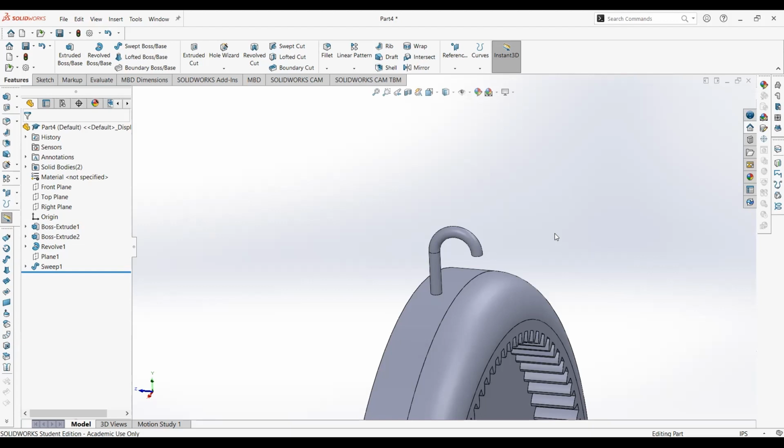Go to circular profile, type 0.125. If you wanted a different profile shape, like a diamond or a square, you could use that tool. But for a circle, the circle was just to show you how to use that tool, and you can do it without it. All right. Are you good back there?